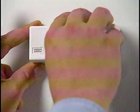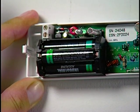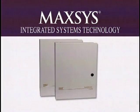If the unit flashes and beeps, most likely the batteries are good, they are installed correctly, and the transmitter is functioning. If you are having a problem, it is most likely a programming issue. If the tester does not beep or flash, the cause of the problem could be a variety of different things, such as bad batteries, batteries installed incorrectly, or a defective transmitter.